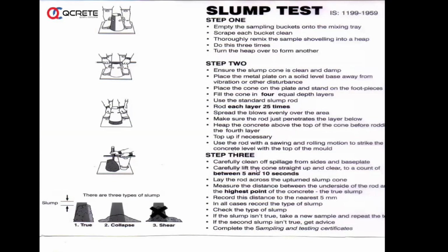IS defines properly how you have to do the slump test. You might have all done this procedure. In this slump cone, you have to take 3 layers, each layer 25 strokes, and then when you lift the cone, how much it falls is referred to as slump.